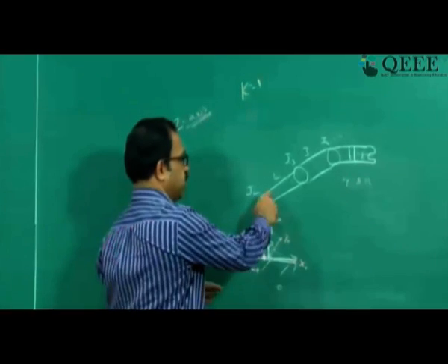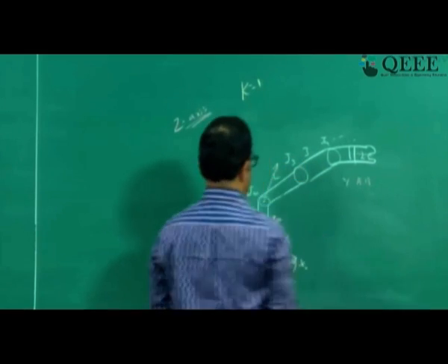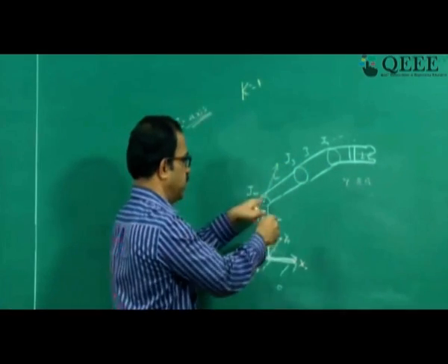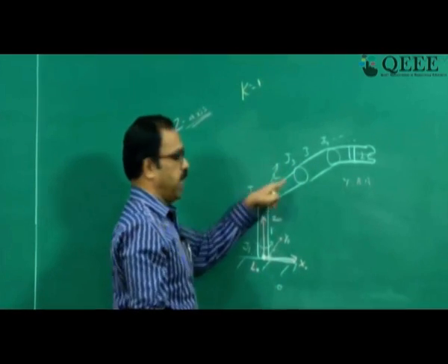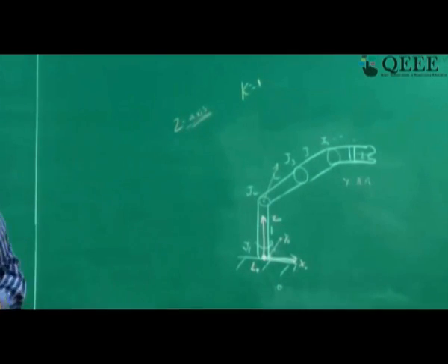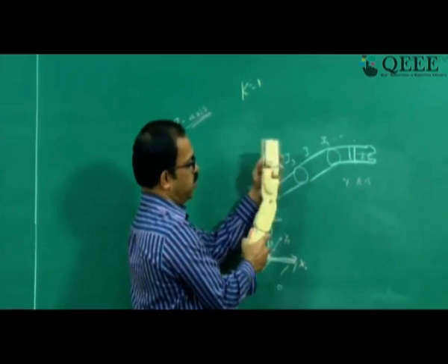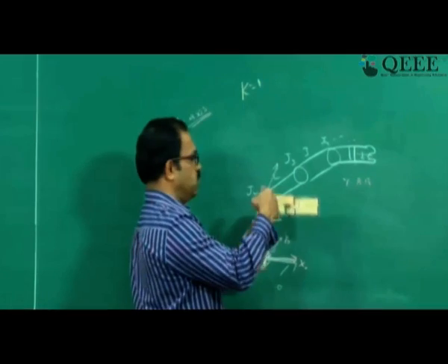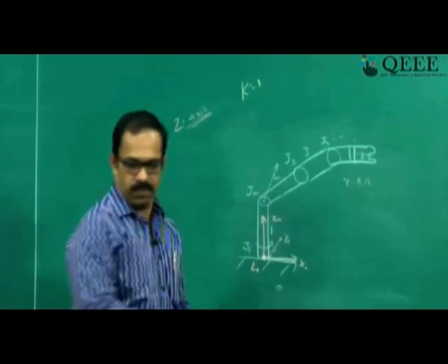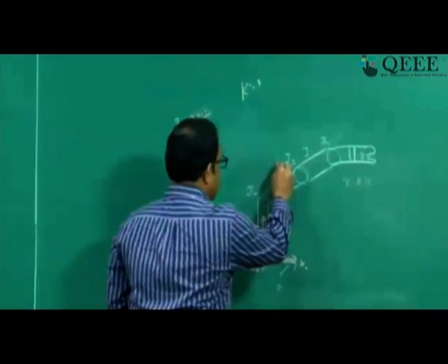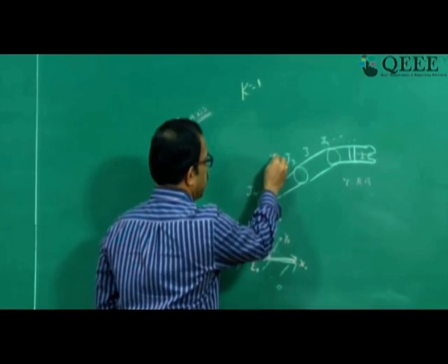We know that this is rotating with respect to this axis, and therefore the z will be in this direction, that is actually projecting into the board. It is rotating with respect to this axis, and it is moving up and down, and therefore we will be able to see that this is the axis. If you look at this, it will be something like this. So this is the joint. You can see this is the joint which actually moves, and this is the axis. This axis is actually projecting into the board, so we will take this as the joint axis here. The joint axis can be like this, it can be like this. So this is the Z1 axis.